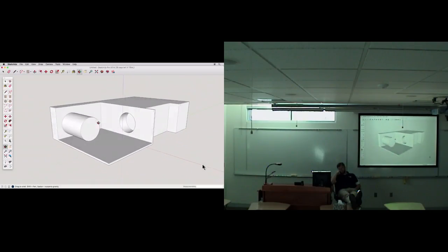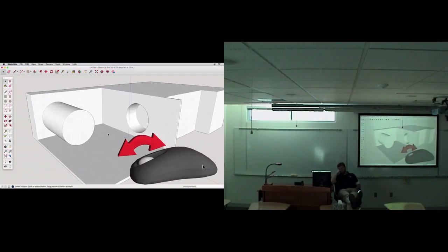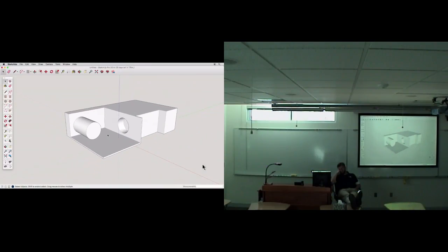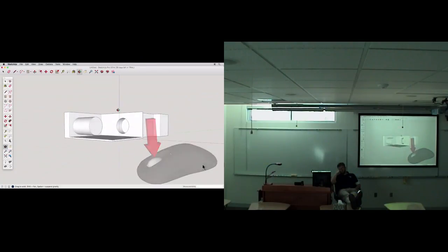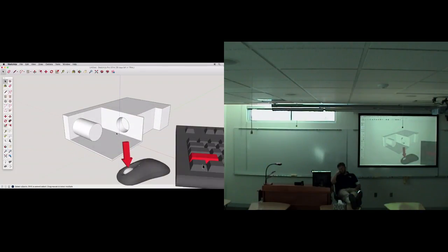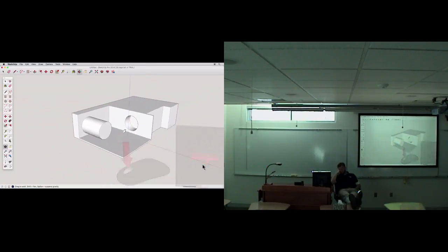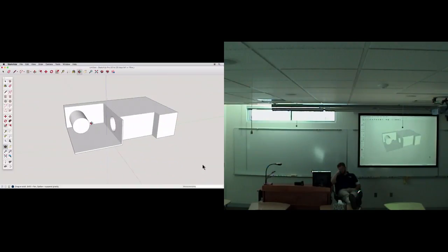Navigating is essential in SketchUp, but going back and forth to pick these icons seems slow and cumbersome, which is why we've built all the navigation tools into a 3-button scroll wheel mouse. Simply roll the mouse wheel forward and back to zoom in and out. Press the wheel down to orbit. Press the wheel down and hold the Shift key on your keyboard to pan. Practice navigating again using the scroll wheel for a much faster experience.